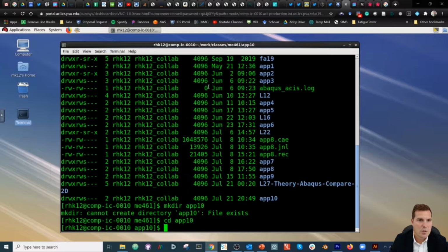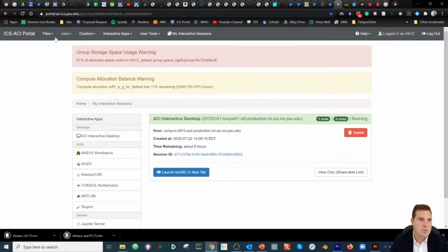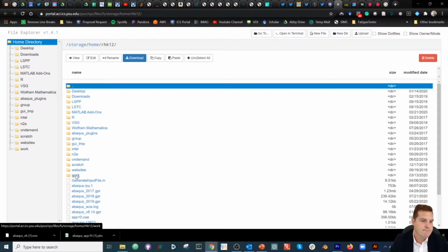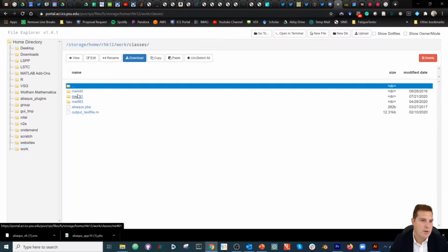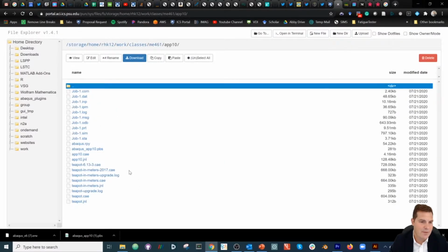Okay. The next thing we need to do is get some files over there. So we're going to go back to Canvas and we're going to download the CAE file I provide to you. You can also do the PBS script and the Abaqus teaching license. So grab those here, just click those to download. We'll then go over to the File Explorer on the portal and upload those. So I have to navigate into that directory, app10. You can see I actually ran this already. I was doing some testing. So you can just drag and drop those into the directory.